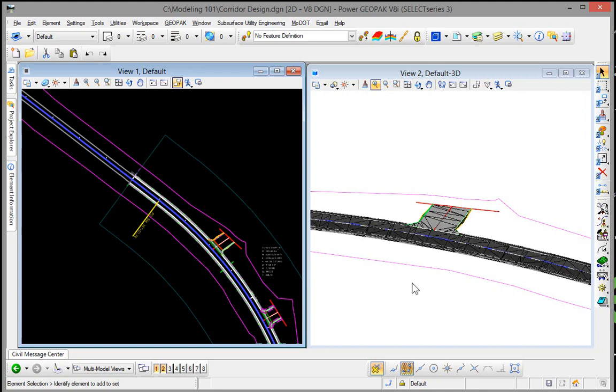Then when you're ready to start designing your special ditch profiles and blending in with your side roads, your slopes and so on, you can activate your existing terrain and allow those slopes to draw, and then you'll be able to fine tune those adjustments as well. So hopefully these tips will give you some ideas to think about in your design process and can help you expedite the processing speeds.